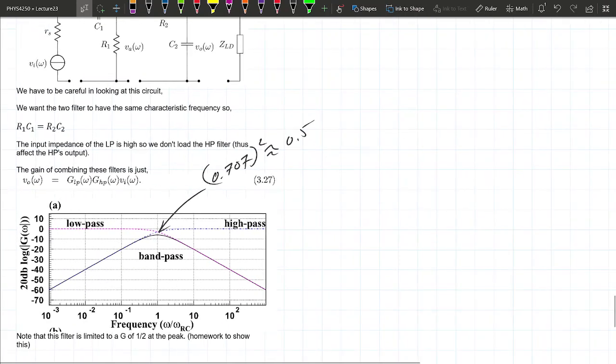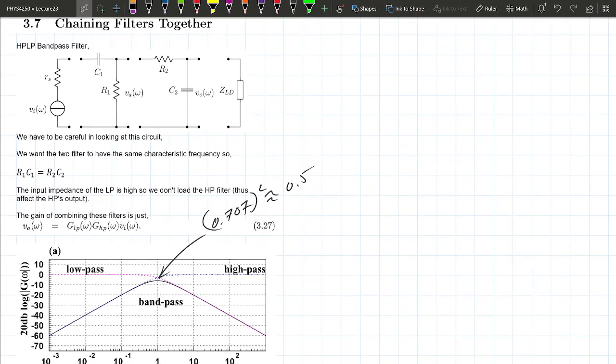All right. Hopefully this makes sense, where you piggyback a high pass filter and a low pass filter together. You get both, but you lose 30% with each filter you use. You only retain 70% on each filter, and when you do that twice, you only get half of the stuff back. Actually, this is an exact number, because this number is 1 over square root of 2. Let me square it. Exactly 1/2.